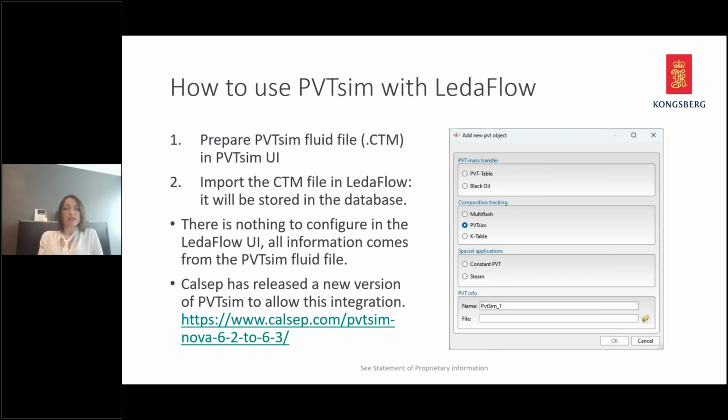If you want to use PVTSim in LedaFlow, it's a little bit different than Multiflash. You will first need to work in the PVTSim user interface to prepare a PVTSim fluid file that has the extension CTM. And then you will import this CTM file in LedaFlow. As soon as it is imported, the information it contains is stored in the database, which means that it is independent from the file itself. There is nothing to configure in LedaFlow. All information will come from the PVTSim fluid file.